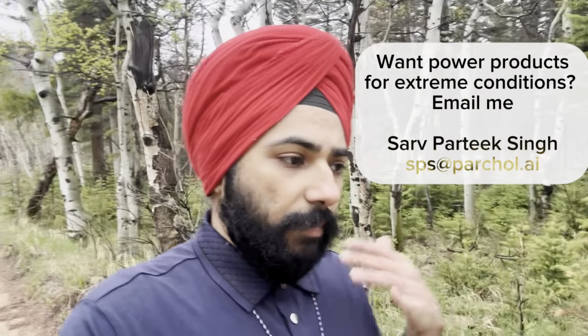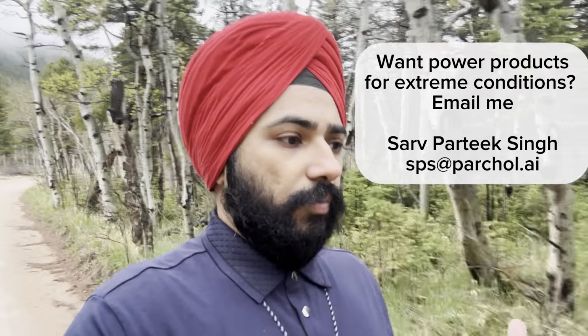So let's take an example of hardware, right? For example, we're currently working on designing an improved front-end converter for our devices. To do this, first of all, we looked at our current products and we saw, okay, where can this product be useful? And then based on that, we looked at its performance, we saw the gap, and then we realized, okay, an improved front-end converter should have this particular specification. Once that specification was drafted, we then went ahead and said, let's look at how we can mock this. So to mock, in case of electrical systems, we typically first start by designing a schematic system, which is then simulated using LT-Spice.